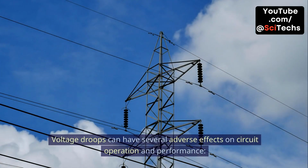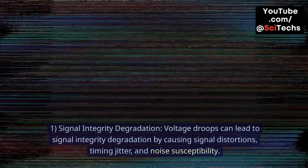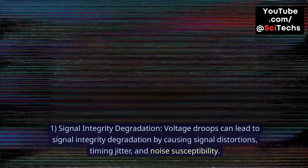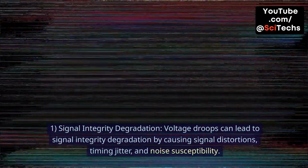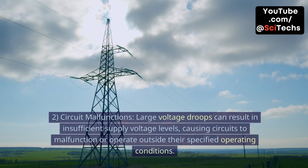Voltage droops can have several adverse effects on circuit operation and performance. 1. Signal integrity degradation. Voltage droops can lead to signal integrity degradation by causing signal distortions, timing jitter, and noise susceptibility. Rapid fluctuations in supply voltage levels can introduce noise into signal lines, leading to data errors, timing violations, and signal integrity issues. 2. Circuit malfunctions.